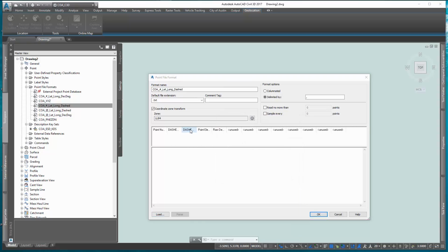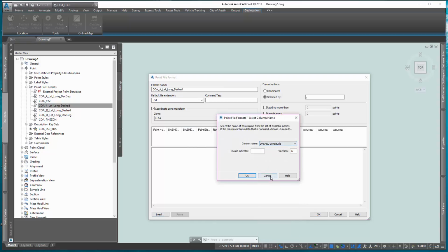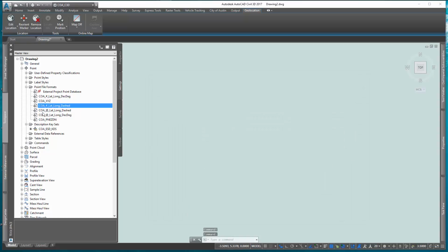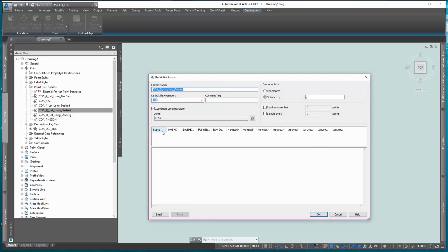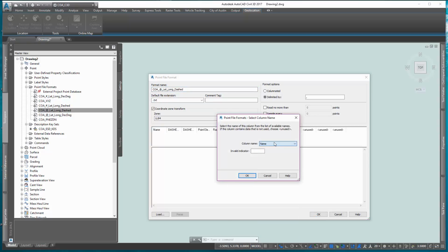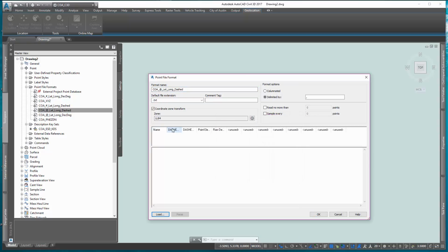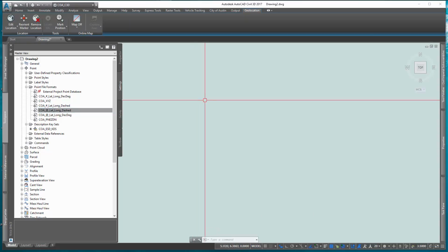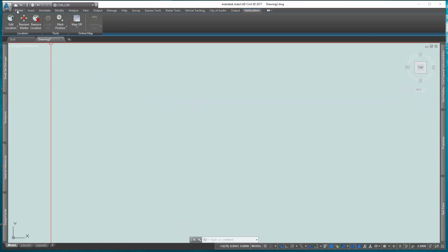You're going to see that one of them has a pound. This is the one used when you have a point number in front, and the other one is used for the name. So we're gonna look at the one with the name. Again, if you look on the top here, there's a check mark for LL84. You have to make sure that it's set that way, because the lat longs were set in LL84, and that's the coordinate system it's imported from. And you're gonna see that one applied in this process.